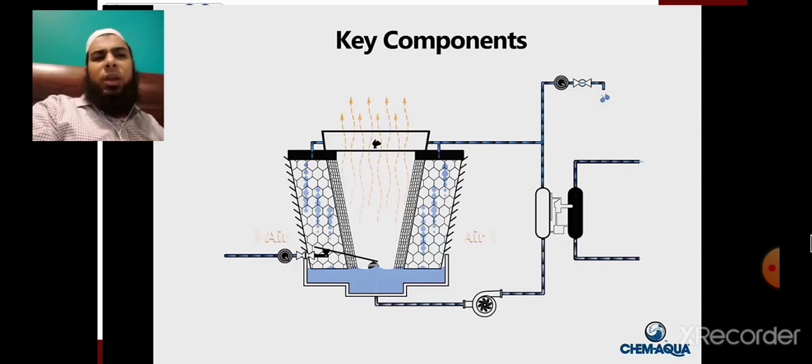So in this way, cooling tower circuits have a high COP, coefficient of performance. You already learned that the performance of a refrigeration circuit is expressed in the COP. So the chilled water circuit has a high COP, and the air cooled chiller has a lower COP.